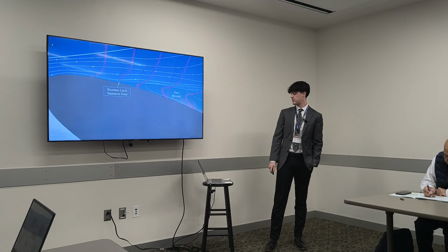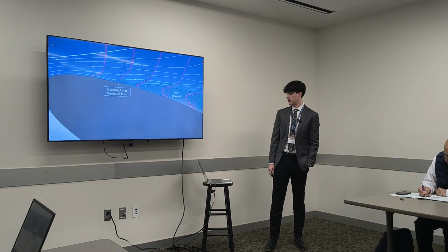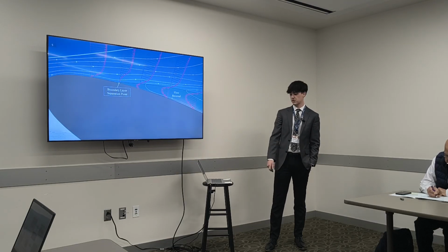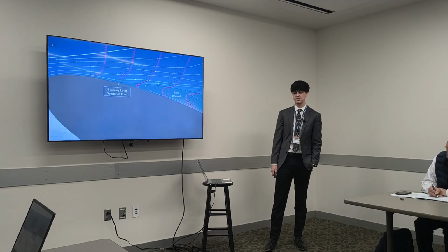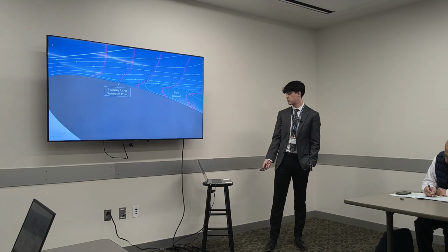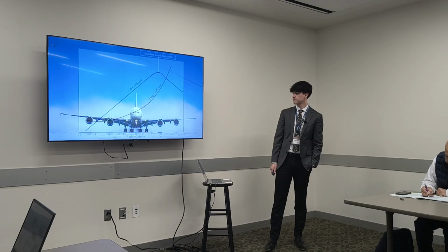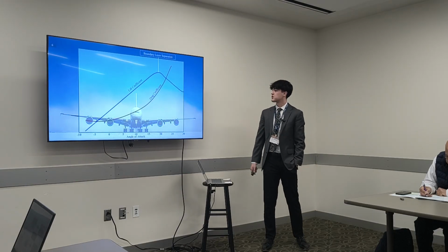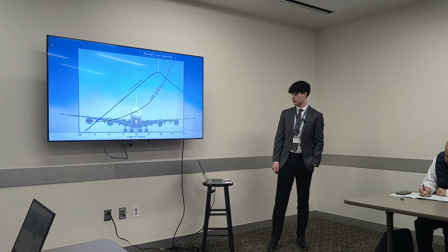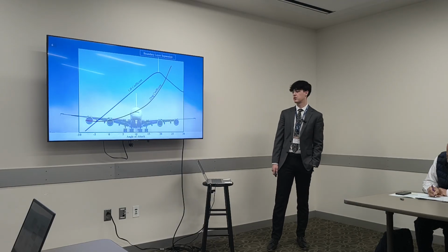And so in orange, we have our boundary layer velocity profiles. And then the dark region is the area of flow reversal. And so flow reversals indicate boundary layer separation. And so therefore, stopping that flow reversal is a good way to prevent separation and keep that boundary layer attached. And so once there is a significant boundary layer separation caused by that adverse gradient, the airfoil experiences stall, which also includes a significant drop in that lift.